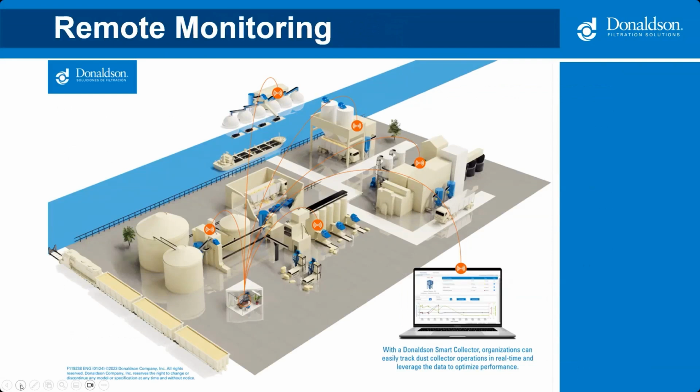Another consideration I wanted to mention is how technology is being used to monitor dust collection systems. So Donaldson came out with their IQ device several years ago to make dust collectors smart. This device gathers process data in real time, creates automated alerts and historical reports, and it's available to customers at no charge. It's a great way for process owners to manage and track regulatory compliance information. So you can monitor static pressure when the EPA, or in Alabama, the ADEM, comes out and wants to see the differential pressure of the collector. That information's all stored there. It also helps you troubleshoot dust collection issues more efficiently.